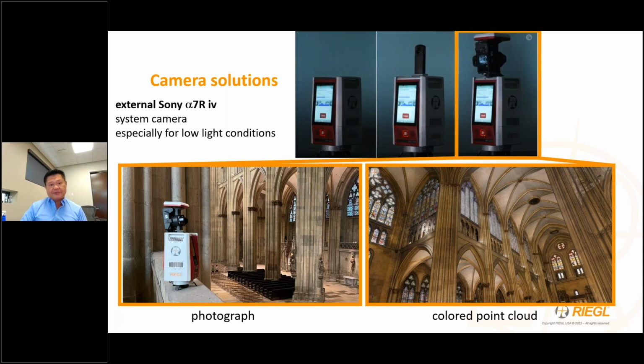So for all three of these camera options, please understand, the images are acquired at the same time, right? As we're scanning and collecting the LiDAR, it's also taking images as well. So for example, just to give you a sense of time, it takes approximately 25 seconds to complete a full 360-degree scan at 6 millimeter resolution at 10 meter range. 25 seconds. We like that number because it's a very good resolution for most projects.